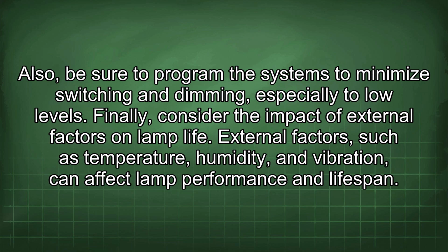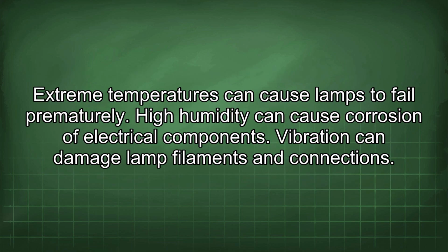Finally, consider the impact of external factors on lamp life. External factors, such as temperature, humidity, and vibration, can affect lamp performance and lifespan. Extreme temperatures can cause lamps to fail prematurely. High humidity can cause corrosion of electrical components. Vibration can damage lamp filaments and connections.